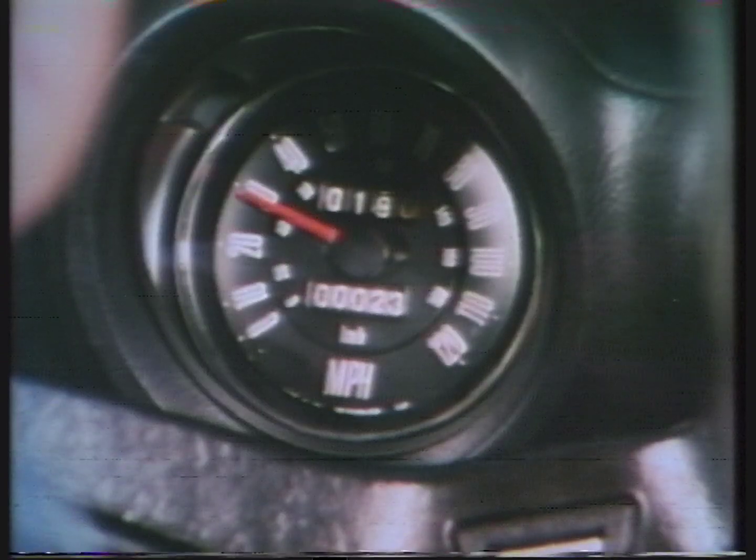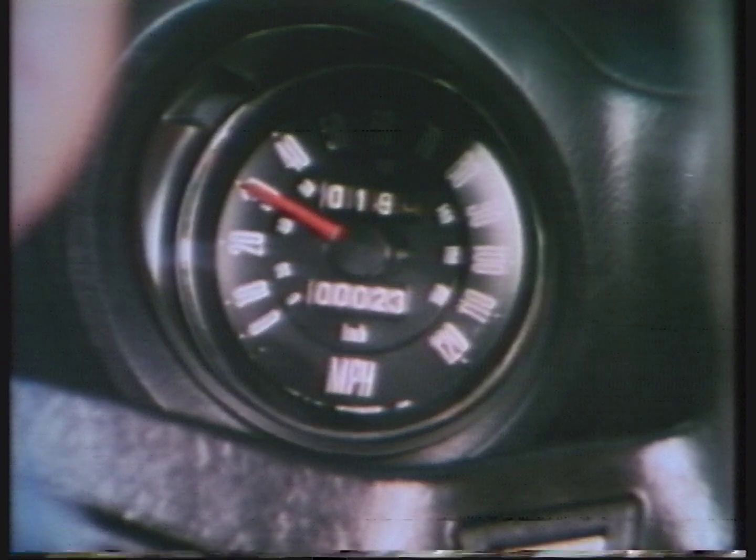If after wheel balancing, vibration still occurs above 35 miles per hour, attention must be turned to the propeller shaft balance, or runout of the rear axle coupling flange. Start by marking the prop shaft at 90-degree intervals with tape. The operator must note the meter reading and identify and note the position of the mark on the propeller shaft, as shown by the strobe light, while the driver must note the speedometer reading, select neutral, and stop the engine.